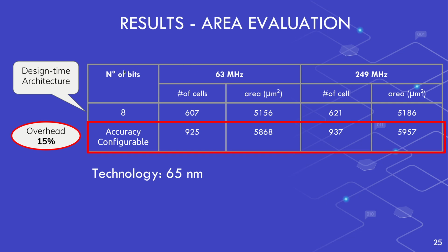In terms of area evaluation, here we have the precise design, considering 8 bits and without the configurable logic. And when we consider the accuracy-configurable solution, we have an increase in area for both frequencies, and this overhead is about 15%.